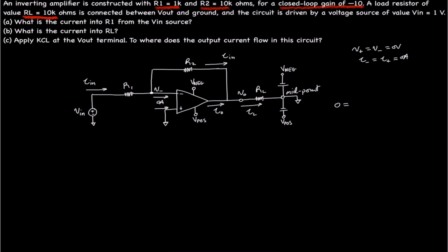So the voltage across R2 is R2 divided by R2 plus R1 times Vin. Then we set Vin equal to 0, take the voltage across R1 with reference to ground, and use voltage division to do so. That is R1 divided by R1 plus R2 times Vout.